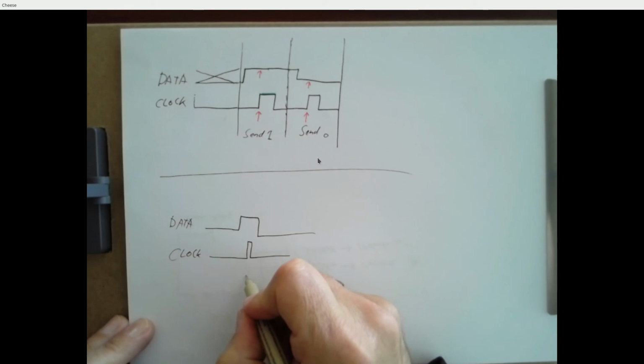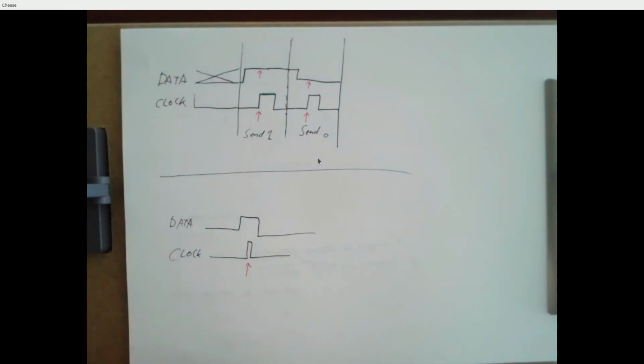So the transmitter raises the clock line. The receiver is in a loop. Okay? The only way you can detect this clock is by polling. Just keep reading the clock input port. Read it, check it, it's a 0. Read it, check it, it's a 0. Read it, check it, it's a 1. Now we do something. But it takes time to go through that loop, right?